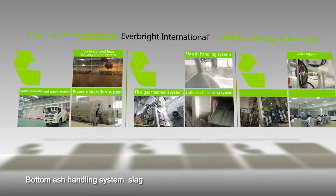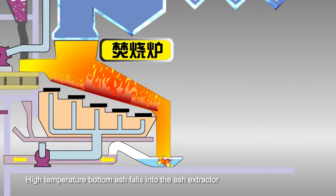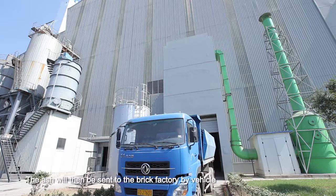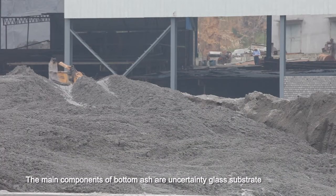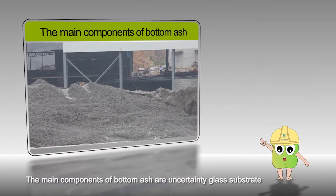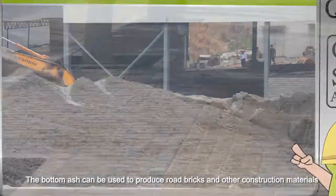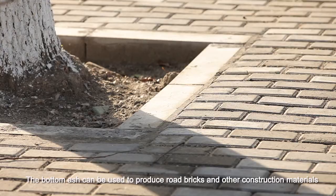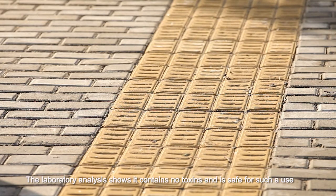6. Bottom ash handling system. High temperature bottom ash falls into the ash extractor for the purpose of water cooling. The ash will then be sent to the brick factory by vehicle. The main components of bottom ash are glass substrate, quartz, calcite, etc. The bottom ash can be used to produce road bricks and other construction materials. The laboratory analysis shows it contains no toxins and is safe for such a use.